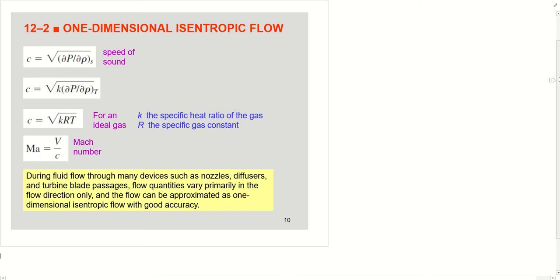As I explained before, isentropic means that we consider the flow to be an ideal flow. No friction is considered in our analysis. Let's say we have a nozzle, with state 1 and state 2. Based on this nozzle, there is a variation of area. As you can see, the area varies from a bigger area to a smaller area.